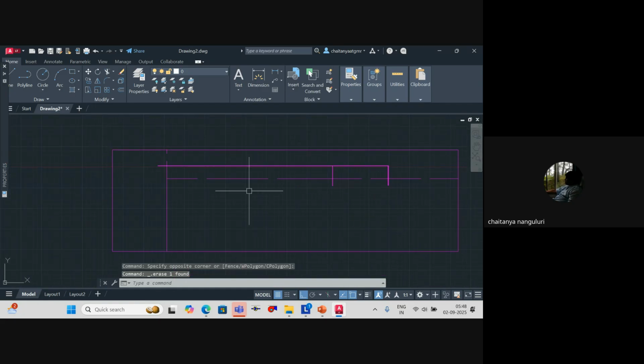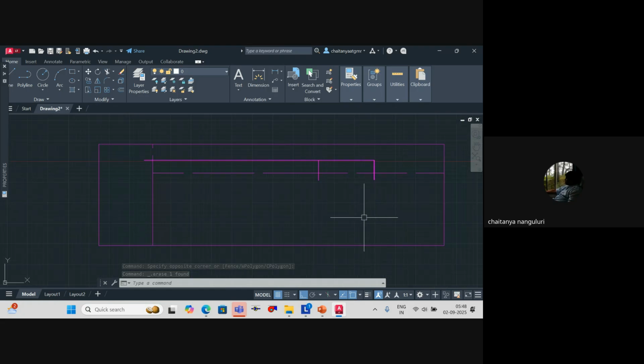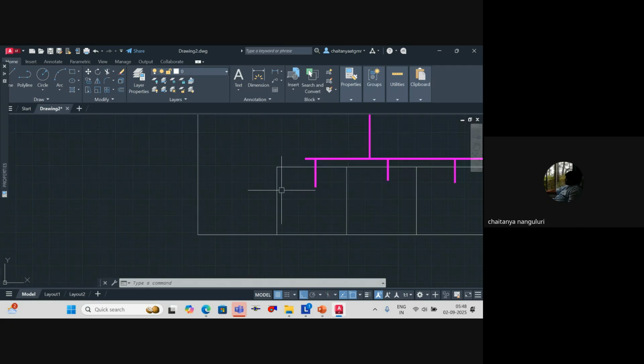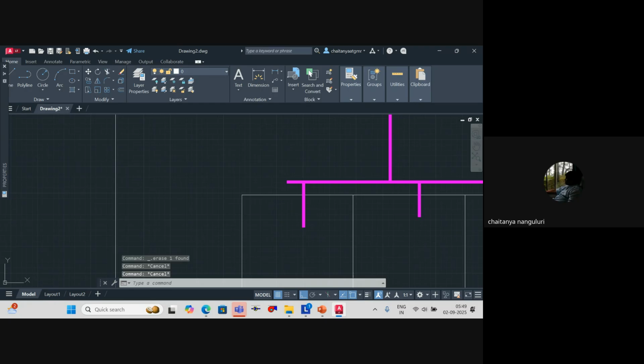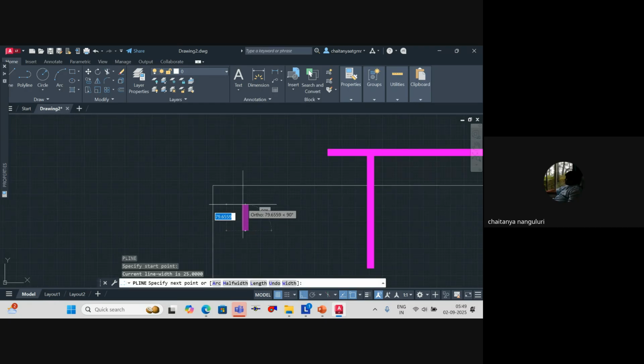So in this case, what is going to happen? Whatever noise there is over here in one cabin, don't you think through the return air it can reach others? That means if someone is outside over here, through the return air, don't you think the voice will be slightly heard at this location or not? Yes, sir. So for that reason, wherever we have a return air opening, we will provide these crosstalk dampers.